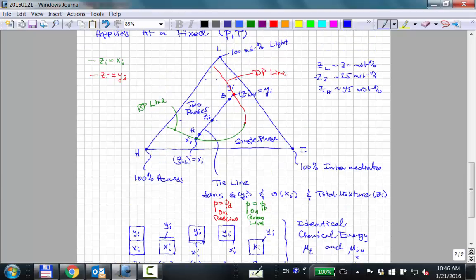Question. Yeah. It's a constant temperature and pressure, right? Right. So what would make Zi move? You're changing the composition. You've got three containers. Okay? I basically go into the lab and I say, I've got a 1,000 component mixture, but I want the lab to distill off only the C1 nitrogen into one container. The middle container is going to have all the components from C2, including CO2, C2, down to C5. All those components, put it into second container. The third container is all the heavy C6 and heavier stuff.